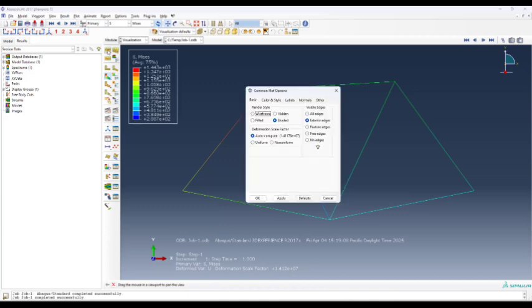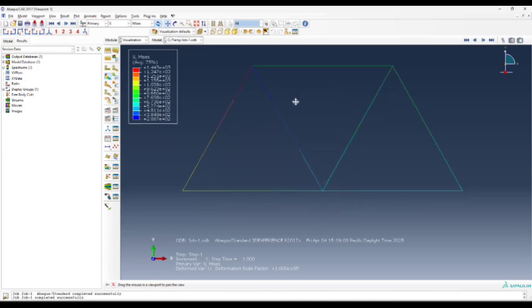So we can press this button right here, common options. We can do auto compute. It's auto computed to be 1.4 times 10 to the power of 7, but we can just do a uniform one of 1. And this is actually how much it's deformed. So you can obviously see it's not deformed at all. The force was just too little and the material, steel, was too stiff for us to really get a deformation. That's why you have to increase the deformation scale factor to really see some discernible deformation.